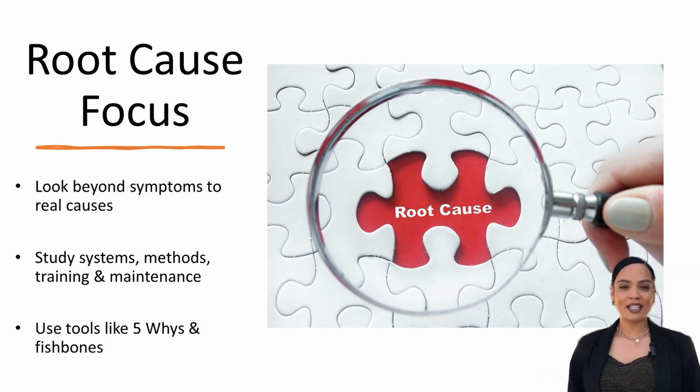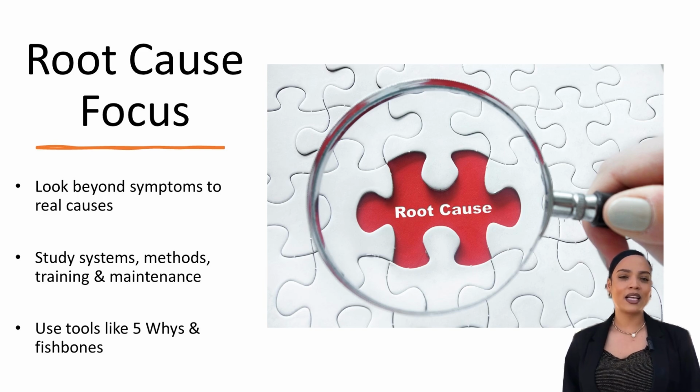Root cause analysis, RCA, is not one specific tool. It is a way of thinking. It means we are not satisfied with surface-level explanations like operator error or machine failure. Instead, we ask, what exactly caused this? What in our system allowed it to happen?